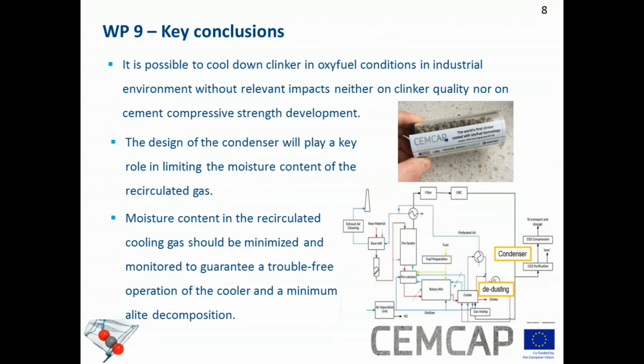What are the key conclusions of this experiment? The most relevant conclusion of all is that it's possible to cool down clinker in oxyfuel conditions in an industrial environment without any relevant impact on clinker quality or on cement's compressive strength development. This is the most relevant conclusion that I would like to highlight.